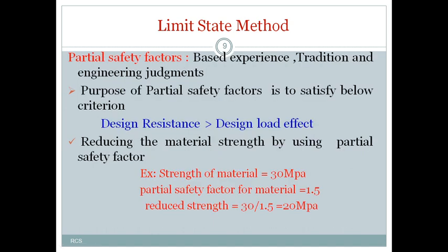Right. Here I said one of the factors to achieve the safety and serviceability of the structure is considering a limit state. Another very important thing is partial safety factors. The values of partial safety factors are based on experience, tradition and some engineering research. Based on those, we can fix the partial safety factor value for a particular material or a particular load. And the main purpose of the partial safety factor is to satisfy the below criterion. What is that criterion? Design resistance should be greater than design load effect.